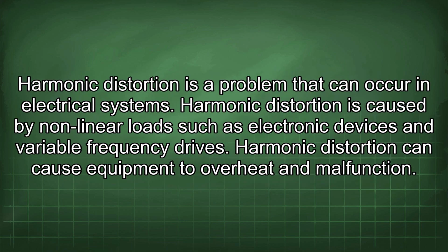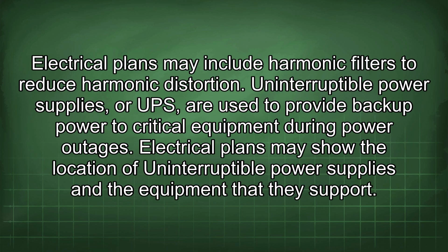Harmonic distortion is a problem that can occur in electrical systems. Harmonic distortion is caused by nonlinear loads such as electronic devices and variable frequency drives. Harmonic distortion can cause equipment to overheat and malfunction. Electrical plans may include harmonic filters to reduce harmonic distortion.